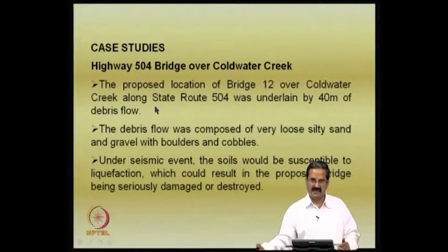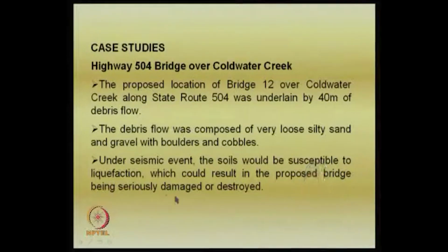There are some case studies here. One is a bridge location, and the soil in this case was a loose silty sand with gravel and boulders. Under a seismic event, the soils would be susceptible to liquefaction, which could result in the proposed bridge being damaged or destroyed. Studies show that the soil has a tendency for liquefaction, and it may give a lot of difficulties to the proposed bridge, which means that the area should be compacted. In the field, of course, we have studied many methods, for example, dynamic compaction.